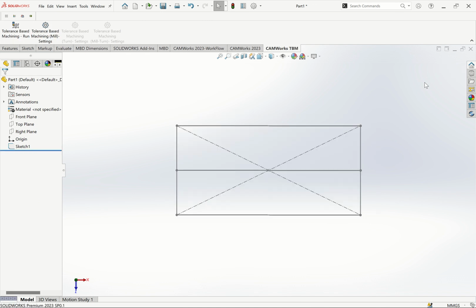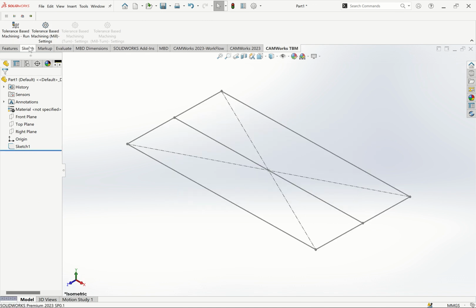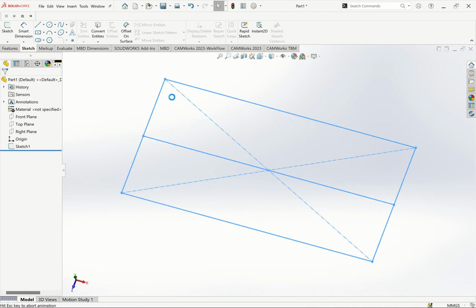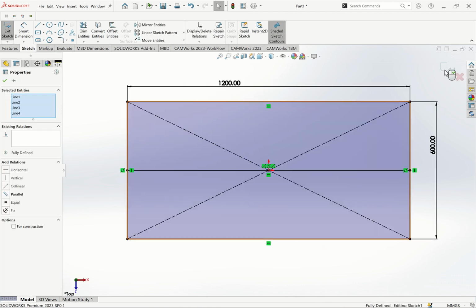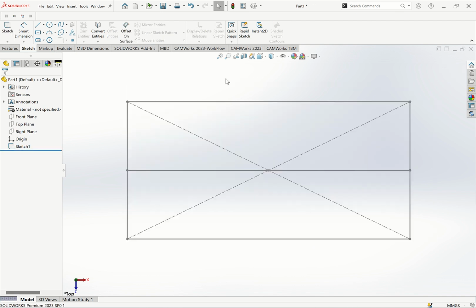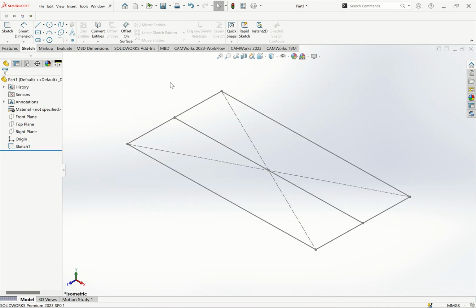That's 2D sketch. Then you go to 3D sketch. Say you're combining, so come to sketch again. First of all, once you finish here, make sure you click here, exit from the sketch. Then Control 7 to see this is our sketch. Then go to sketch again. Down here under sketch, click 3D sketch or select 3D sketch.